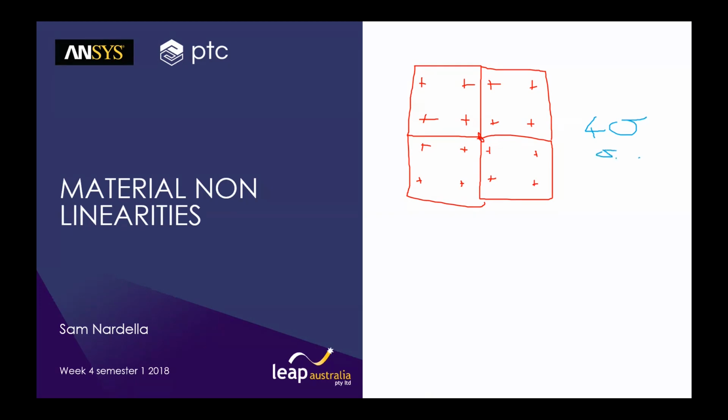And the stress value that's displayed is an average. So if you have a mixture of stress states, so here if this one is plastic, when it's a plastic stress state, it's copied to the node. Okay, so these are all elastic. And because we're dealing with a spatial extrapolation, it's distance-based.